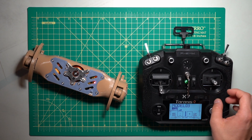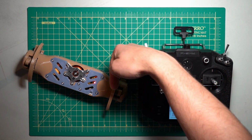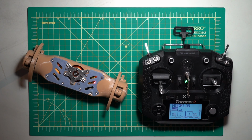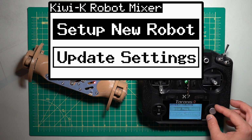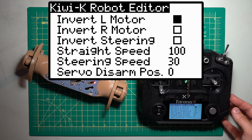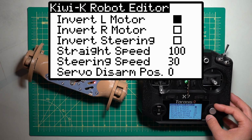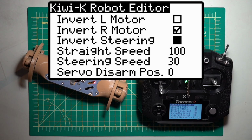When I press forwards on the stick, I can see that the left side of the robot moves forwards, and the right side goes backwards. Because the right side is going backwards, I know I have to reverse the right motor. I'll do this by entering the editing menu, then just selecting the checkbox to invert the right motor. And that's it.